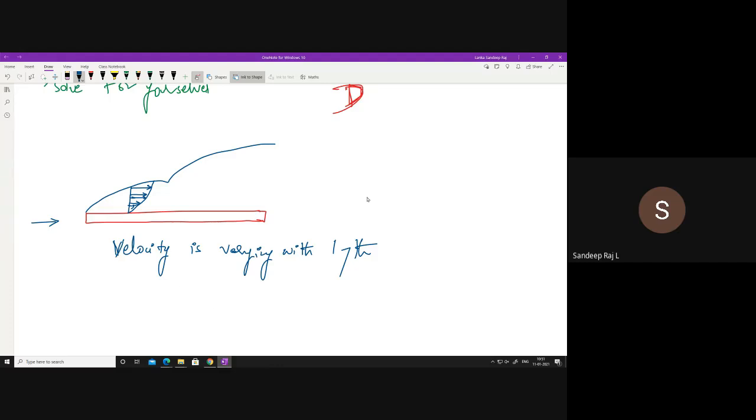See, all the formulas, the Nu, are related with some Reynolds number. Nu is nothing but your non-dimensional H value. Reynolds number is a non-dimensional velocity value. So H and velocity are directly related here. Higher the velocity, higher the H value will be. So the velocity will seriously influence the H value.